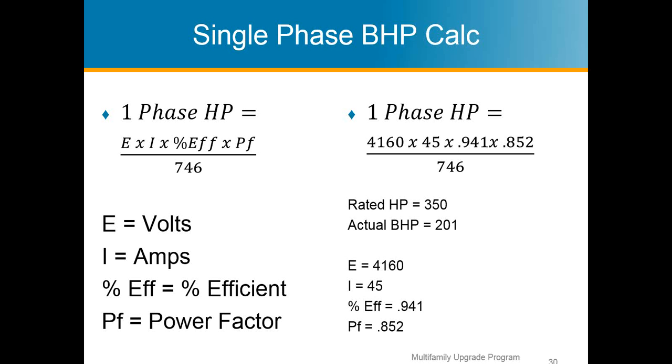It's a lot of information to talk about, so I'm not going to get into too much detail, but it's definitely essential to understand how fans work and how to calculate brake horsepower, because you are going to want to put that in your energy model as brake horsepower. And if you have it in as horsepower and you're seeing that your actual is super high, definitely go back and check your fan energy and make sure you got it in as brake horsepower at its operating conditions.